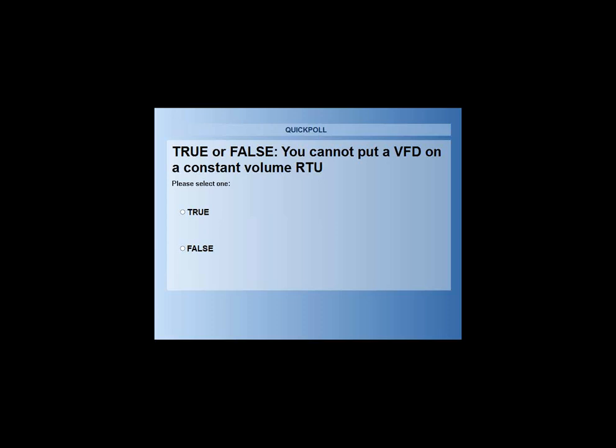Boris says it seems that this system is for 100% OA buildings, regarding the ERV question. That is not the case. We do ERVs on a lot of buildings that don't require 100% outside air. At 100% outside air, it's code required to have an ERV. But we do a lot of ERVs on jobs that are 35, 40, 50, 60% outside air because the payback's there to do it. And you can have the separate transitions in the ducting system for that to happen. So if you need help with that, let me know. I can help you guys with that.